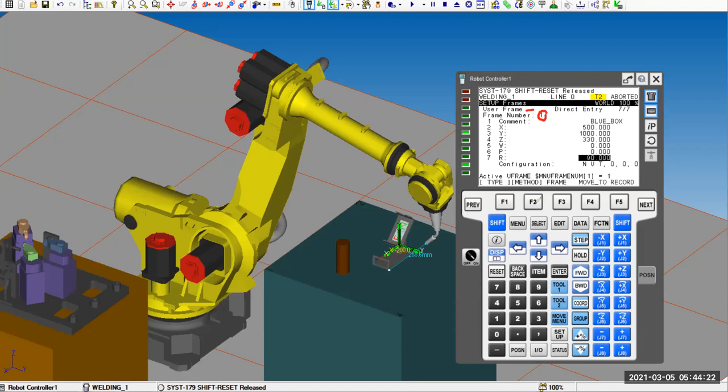If it's not direct entry, you need to press F2 to get direct entry. Then you need to enter those values, right? Because I asked you to use the 3 point method, you may get a different result, right? But in order to move on, I need you to have this unified result on the user frame, right? So I'll clear it up so you can look at it.